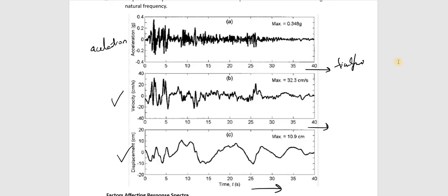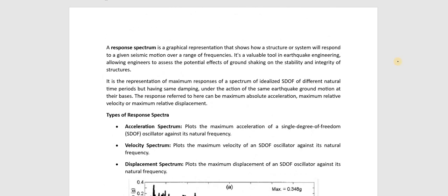So response spectrum, we can say, is a graphical representation of how a structure will respond to a given seismic motion over a different range of frequencies.